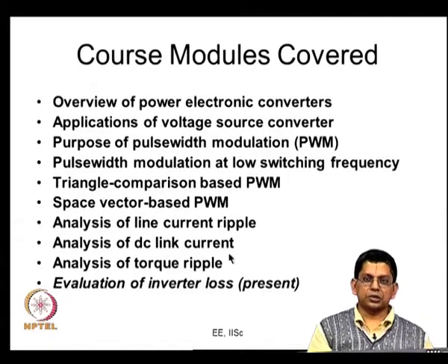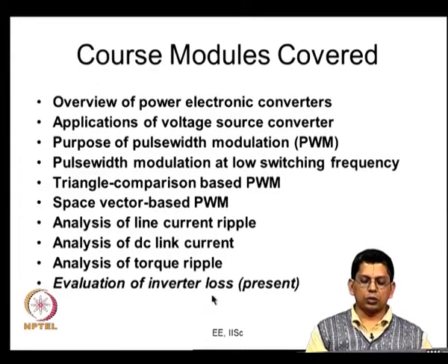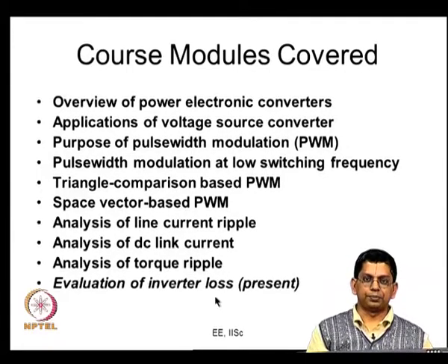So, the RMS capacitor current and the equivalent series resistor of the capacitor can give us the loss in the capacitor. Here our focus has been essentially on the semiconductor devices in the inverter. There are two significant kinds of losses: one on account of the forward conduction, which is called the conduction loss, on account of the forward drop, and the other loss is on account of switching.